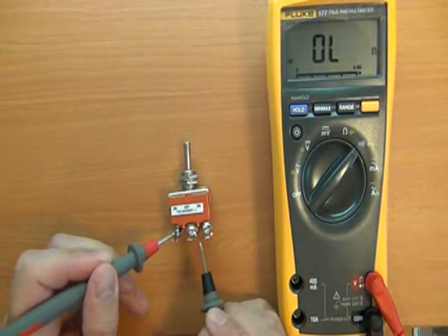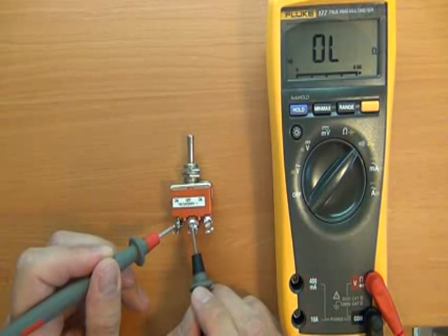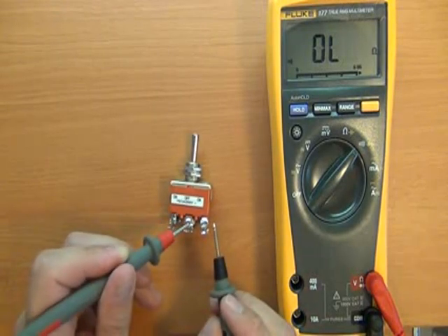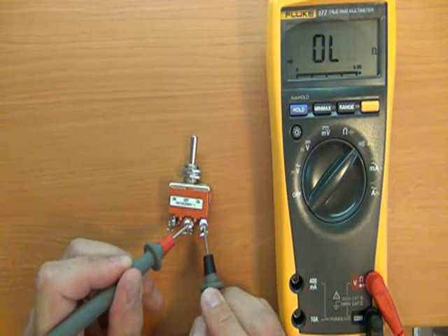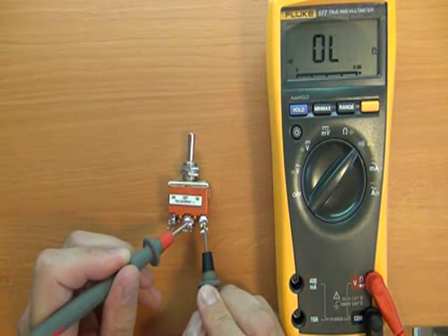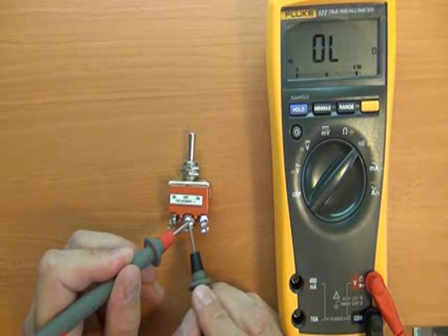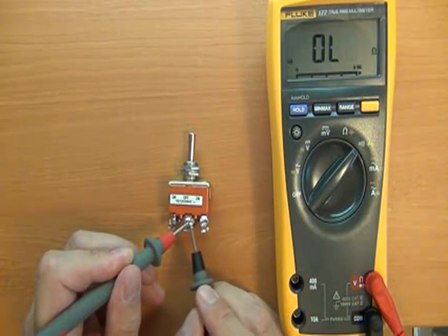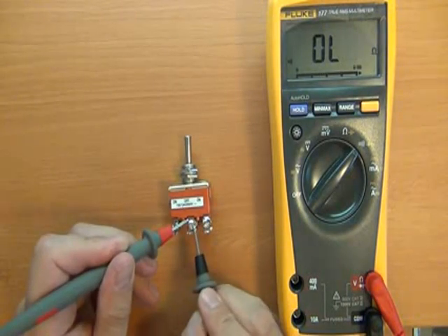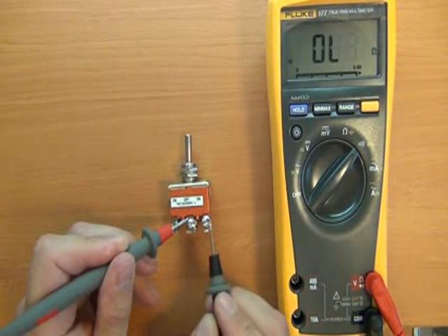So if I put my one probe over there to see if there's flow or a connection between these two points, nothing. If I put it there and over here, nothing. What I generally do when I'm doing this, because I always want to check that my multimeter and my probes are working, is sometimes come back to where my initial probe is. I might not directly touch the probe, but I touch the same piece of wire, the same piece of contact, to make sure things are working.